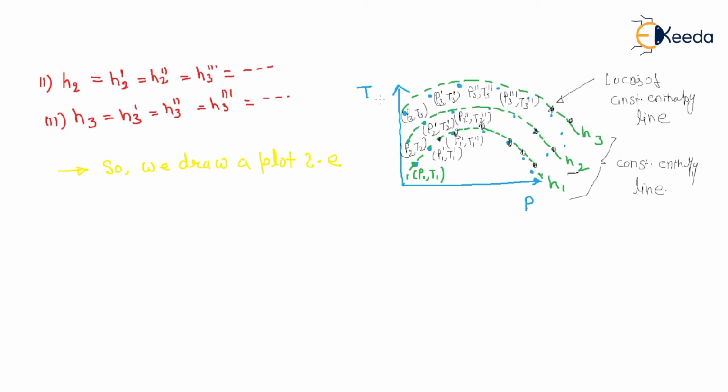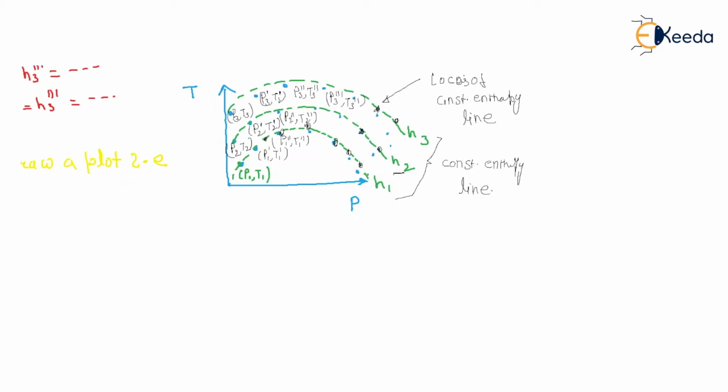Again you change the inlet condition. So repeat the inlet condition, corresponding to that we have an enthalpy, fix the enthalpy, and you regulate the valve. That means you gradually close the valve, and we found different P and T sets, and all those P and T sets lie on the same enthalpy line. So if you do so, this will look like that.